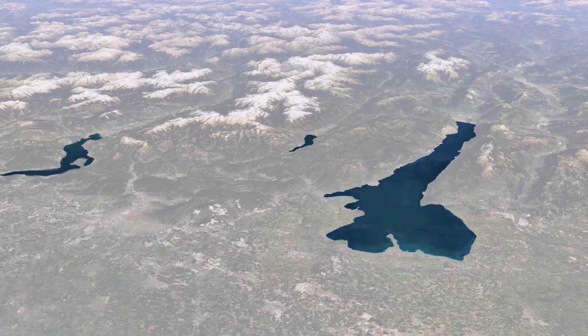Another frequent difficulty in real-life engineering problems are unpredictable areas within the design space caused by erroneous design evaluations during execution. We can imagine the Blue Lakes in this view being such erratic zones, without any result for elevation height in the Z direction. It becomes evident that an optimization algorithm needs to be able to do both: cope with error designs, and invest computational resources smartly in promising realms of the design space.